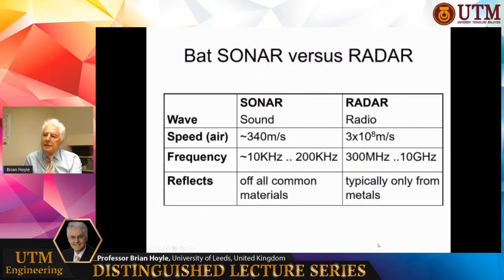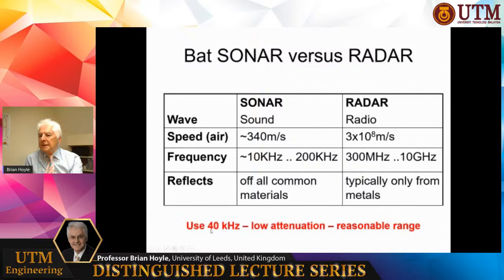If we contrast that with radar, that sounds like a possibility, but radar only typically reflects well from metal. So sonar is a really good choice for this. And I'm going to suggest that we use 40 kilohertz because it's well into the ultrasonic area, and it will give us very good spectral things. We're going to look in a second at the resolution we get from this higher frequency sound.